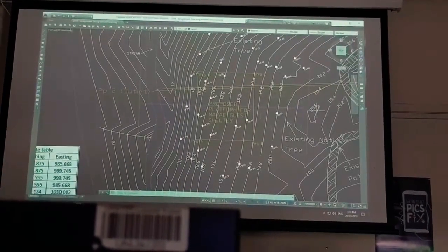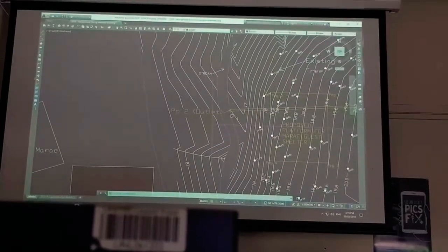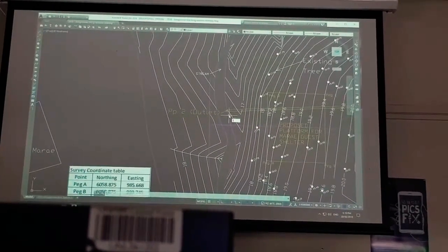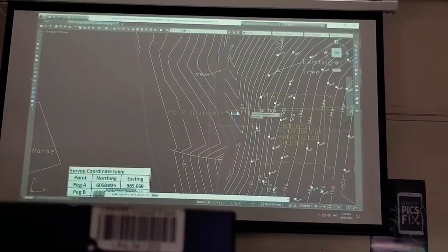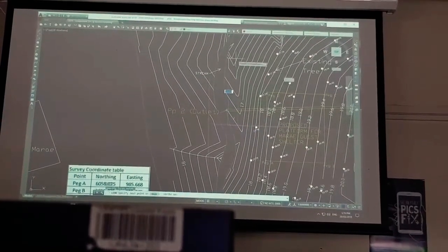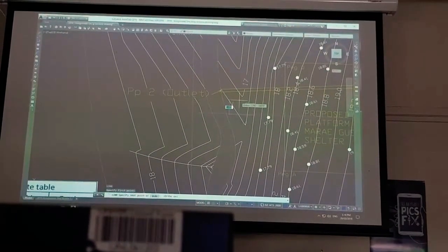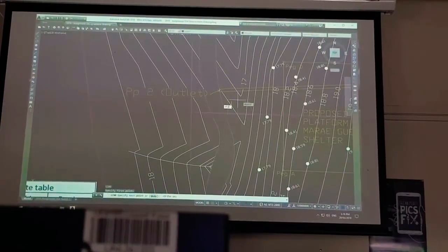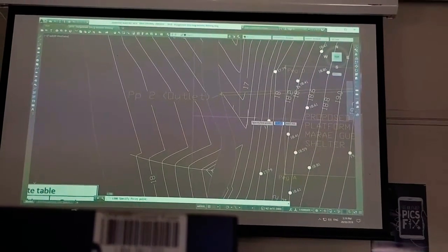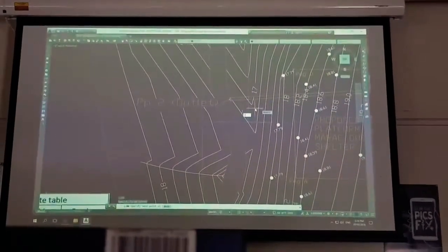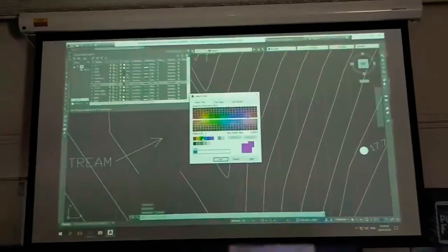So I'm going to go ahead and draw the ground line, and as you all know, it's natural, so we just draw a line from here, for example, up, that'll be 17.2. So I'll aim upwards and type in 17.2. A line from here on the same contour, 17.2. A line.